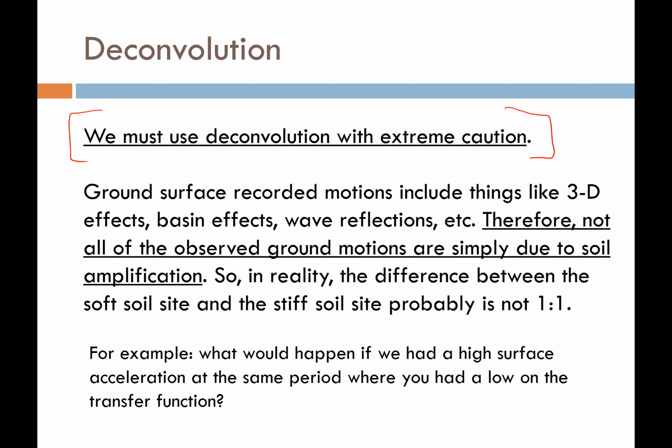So a lot of these things, 3D effects, basin effects, wave reflections, aren't going to be accounted for. They're just going to get fudged into that transfer function that we're going to compute. And so the observed ground motions are not all produced 100% from soil amplification. A lot of those observed ground motions are coming from local site effects, like we talked about a few weeks ago.